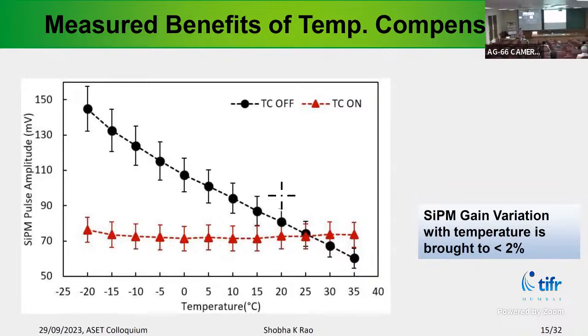So you have a jacket of a heater all around the sensor side. And that is what we used to do for laser. When we send the laser up, we control the heat because it varies the temperature. So you can actually heat the sensor part and fix it at 25 degrees. Within 1 degree, you can control. And it's a ground-based system. You have no problem of power there.